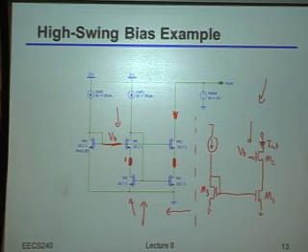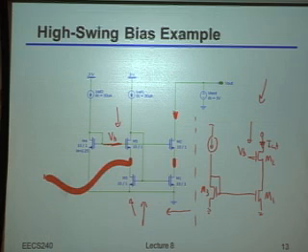Again, really the most important meta point is that anytime you want two things to match, you absolutely have to make sure they are exactly the same. And exactly really means exactly. If one of them has a cascode, the other one has to have a cascode. If one of them has some weird wire going off to oblivion, because you decided to add it there for whatever reason, the other one had better have the exact same thing too. Okay? Now, obviously, depending upon what it is, it'll have more or less effect as to whether or not it'll cause a huge matching error. But nonetheless, if you want to do things right, you had better do things exactly the same.